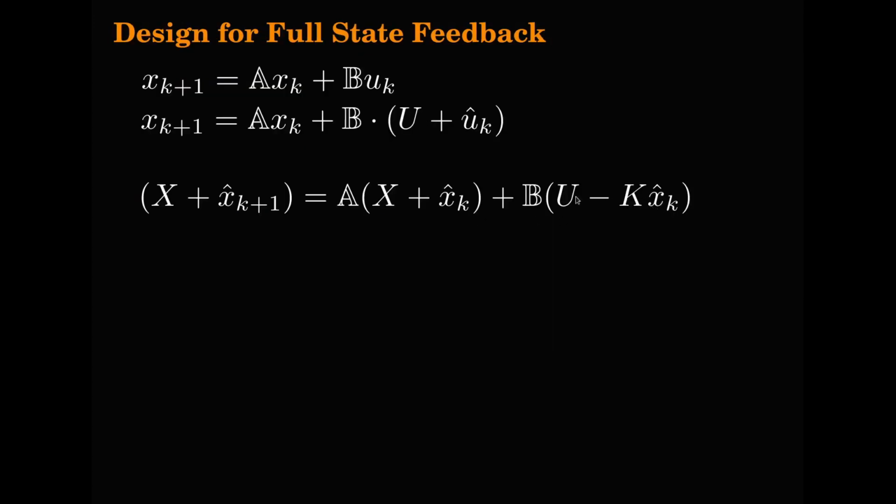So now let us separate this equation into two parts. One is the nominal operating point value part, that is the steady state value part, the uppercase values, and the small signal part, the deviations in the neighborhood of the nominal operating point part. So this is the small signal part. So this varies with time, and therefore you have x(k+1) hat is equal to A x(k) hat minus BK x(k) hat.